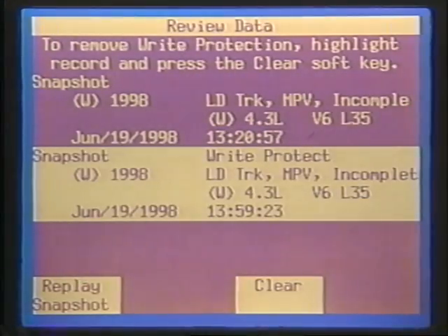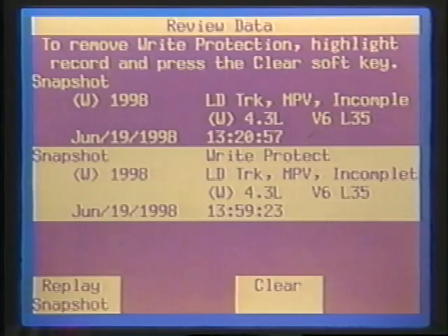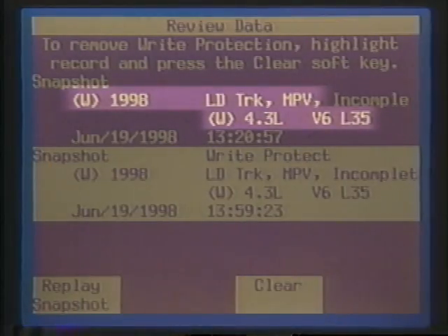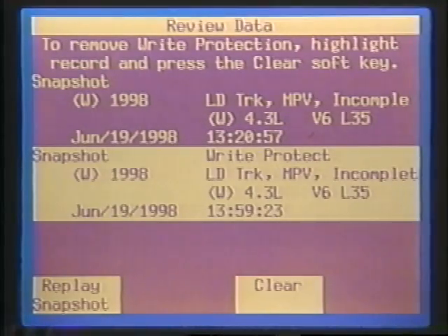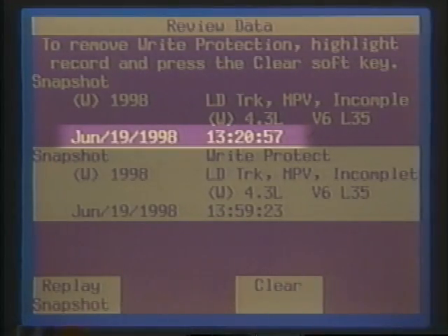And whenever you need to return to a snapshot on either the Techline equipment or the Tech 2, the software will probably show you 2 to choose between. You can tell which one you want by checking the vehicle details and the date and time of the test drive in question.